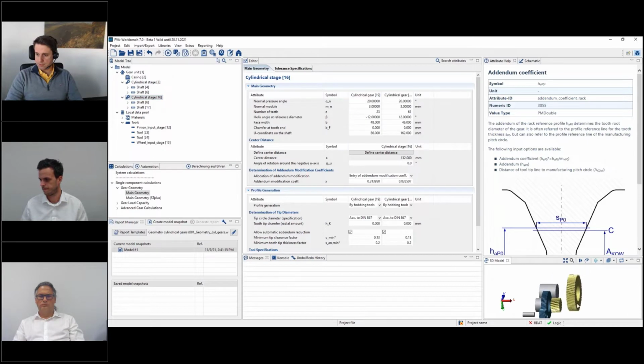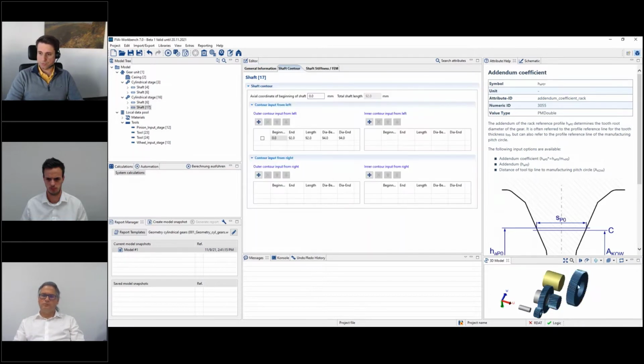Again, here you could see that the position of the gears is slightly off, and this is because I need to change the position of my shaft, and because I need some space here to connect it to our axle. And this is the right time right now to also change the geometry of our shaft. Therefore, I'm defining sections.